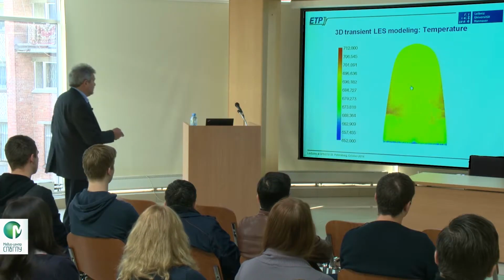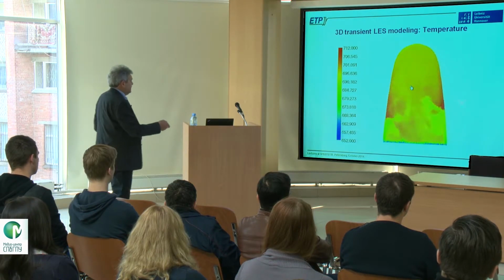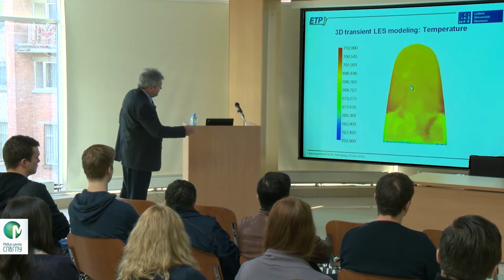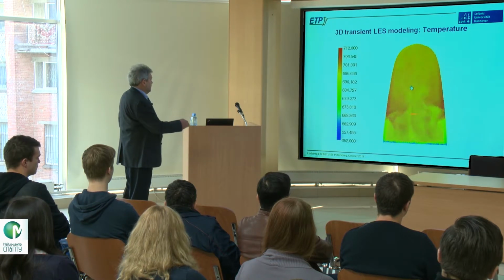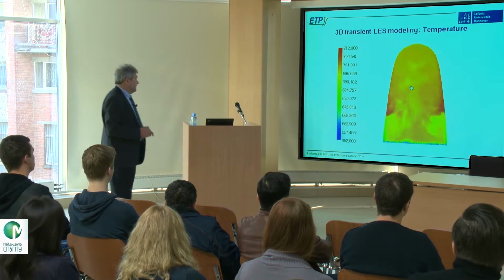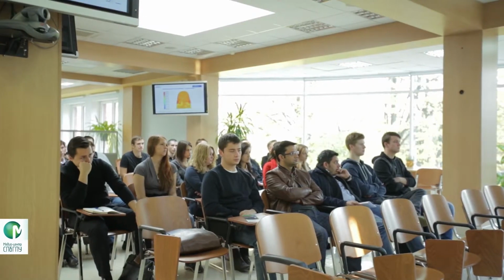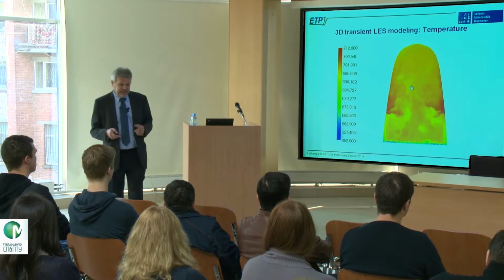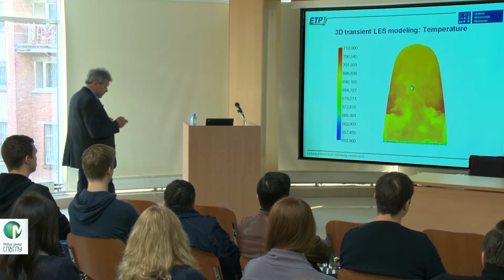You see where the red is the high temperature, of course. Here you see the scale. The main heat is generated here, but it is a strong mixing. And of course, here on the bottom, you see that it is water-cooled. And this is the aim of superheating of the melt. You see that in the top part, it is quite superheated. But in this case, it was 40 Kelvin. The aim is to double it, to bring it to 60 at least, or 80 Kelvin. But today, this is also possible.